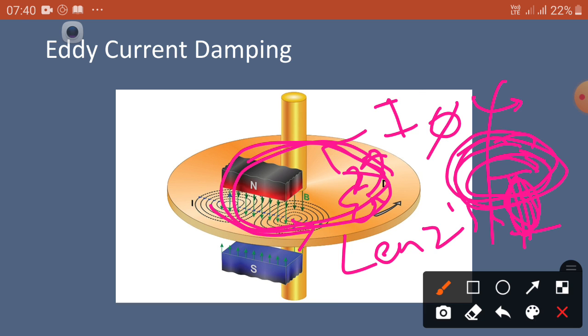If you have observed, in olden days, energy meters had a disc, and in that there is a brake magnet present. By moving this brake magnet in depth and length, that means by cutting more area of the disc, the speed of the disc is reduced.